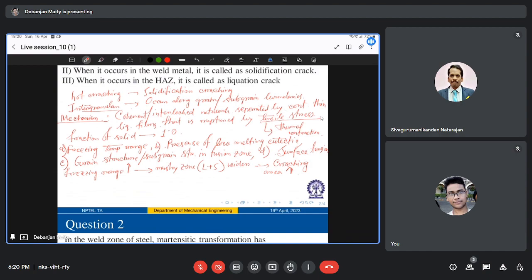Now what will happen at much higher level? At higher level there is such a large effect, and so much liquid is present, that any cracks that form are backfilled, right? And in between is the worst case. Enough eutectic liquid is there to form a continuous film at grain boundaries and render the alloy crack susceptible, but not enough to backfill the incipient cracks.